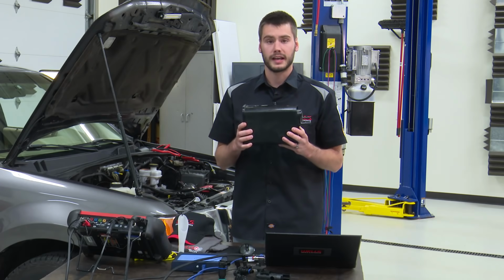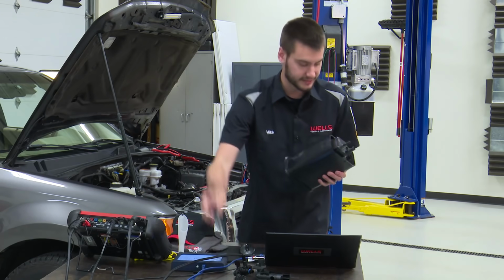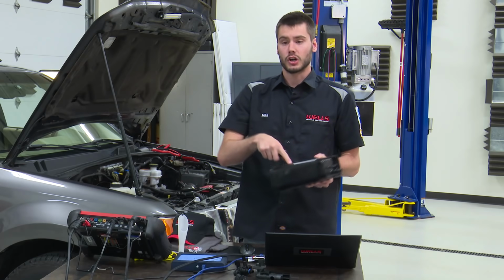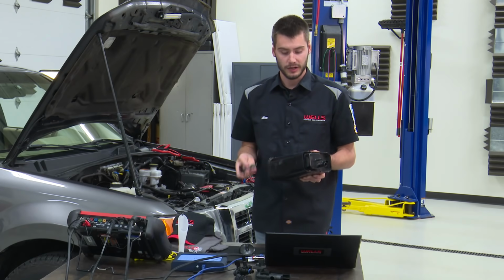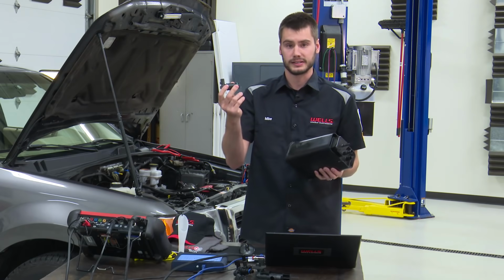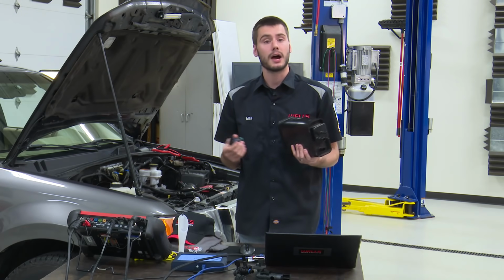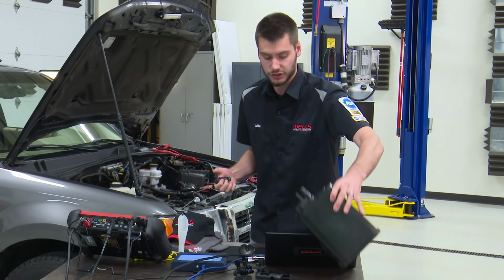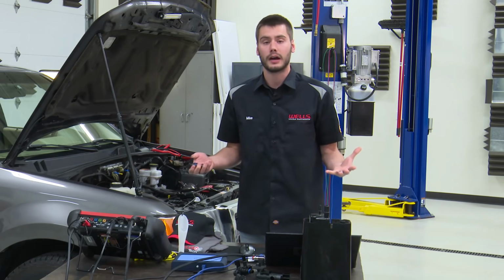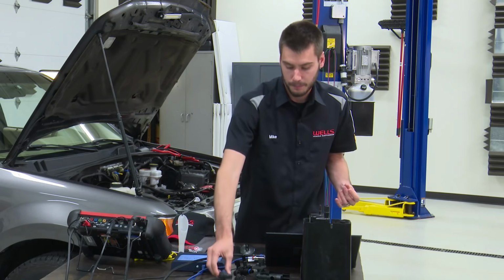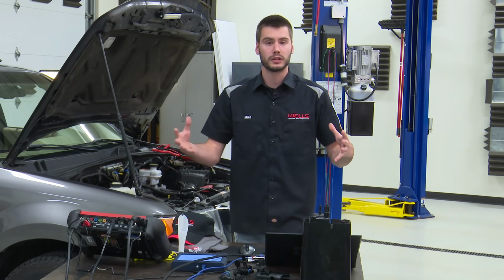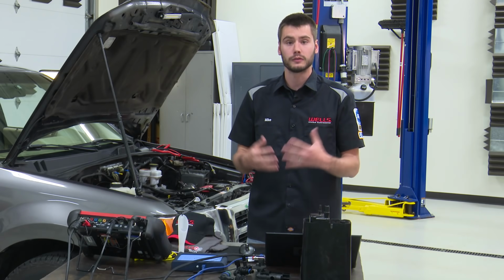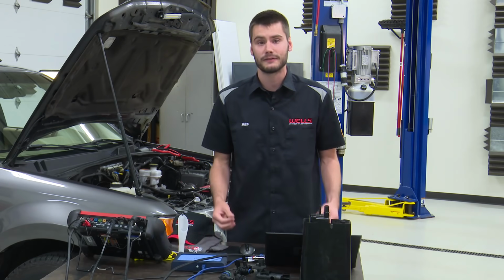So our canister is holding these vapors. Our vent solenoid is connected to it somewhere through a hose or directly in the side. The charcoal in here is able to filter those vapors out and only allow fresh air to breathe in and out of this vent. Therefore, we're not actually allowing any fuel vapors out in the atmosphere, but our system is able to breathe efficiently, because if it couldn't, how do you fill it with fuel, right? You can't have a fuel tank full of fuel and air and try and force more fuel in there without having the air able to go somewhere, right? Or the fuel vapors able to go somewhere. So that is why we have a vented system.